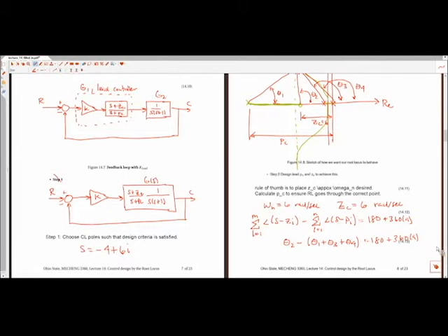Okay. So we know theta 2, theta 3, theta 4, and so now we just need to solve for theta 1. So rearranging this equation, I get theta 1 is equal to theta 2 minus theta 3 plus theta 4 minus 180 minus 360 degree multiples for some integer a. Right. That is our unknown angle.